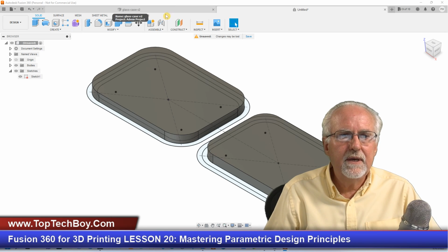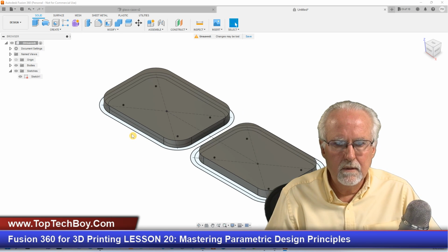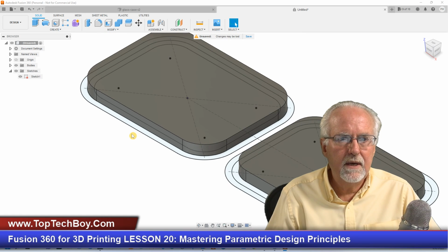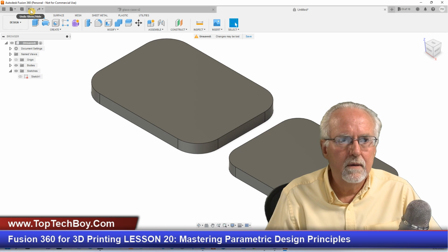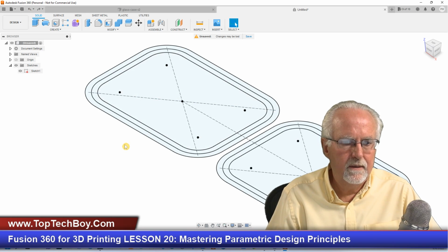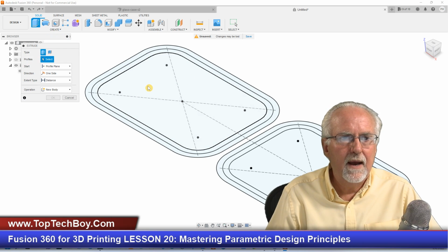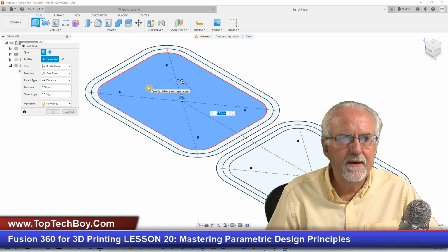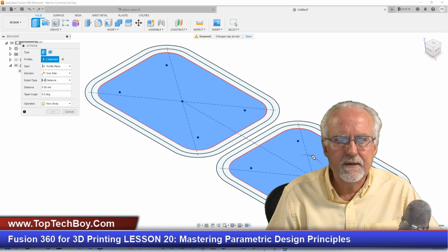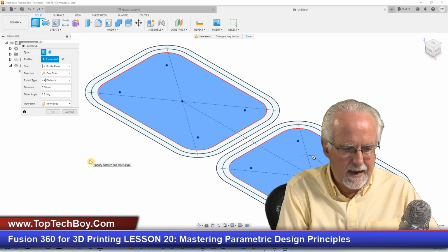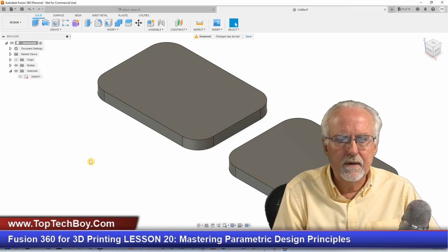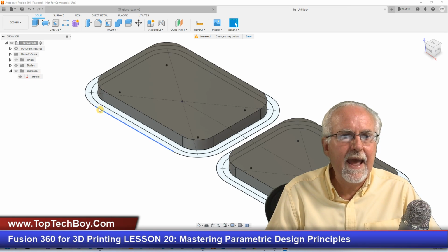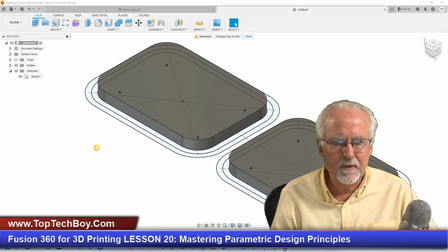Now, I want you to look here. I am going insane. That, for some reason, did very badly. Okay, let me try it again. Somehow I'd selected the wrong thing, so I'm going to extrude. I want to extrude this, and I want to extrude this, and I want to extrude it by case T. Okay, enter, enter, boom. Now I'm going to turn the sketch back on, and luckily this part didn't extrude. I don't know what I did wrong a while ago.